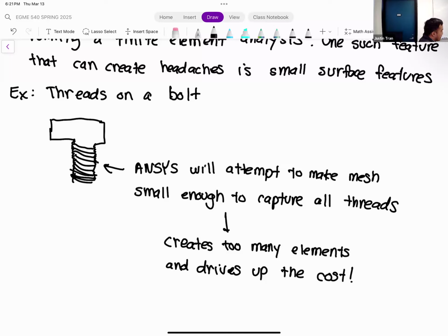So that's probably the most common thing that I see, especially for structural FEA, because these bolts are often included in these CAD models. If you are going to do a finite element simulation with bolts there, maybe you want to find out what the stress on these bolts is. So you can leave them in the model, but you have to have a way to suppress these threads.